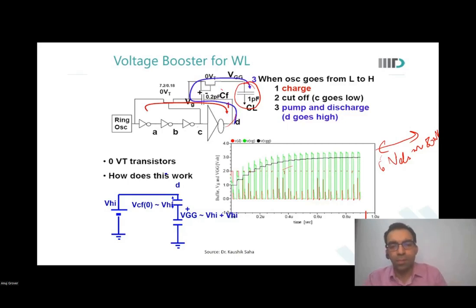Sir, in the early read operation, in the last lecture, we saw that CAS will come later, but there was a jump because the output was high. So how will that be distinguished from junk, data out and junk? Like output was high, no? So junk you don't bother about. You simply latch output only after T access. But memory is giving output based on output access time, right? Yeah. Memory could be giving output wherever. But when do you latch the memory output? That is what is important, no?